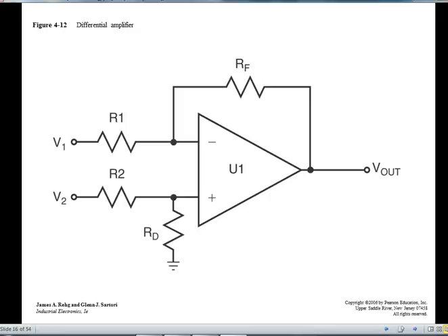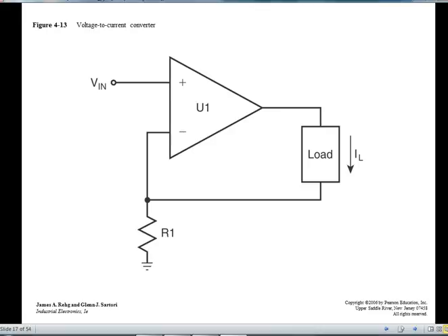I can add this is a differential amplifier. All I'm doing is I'm just trying to figure out what the difference is between the 1 and 2 guy. So this would be a compare amplifier. So I'm comparing signal 1 and signal 2. If I'm positive, then signal 2 won. If I'm negative, then signal 1 wins. And I'm going to be saturated pretty quick when I'm doing that.